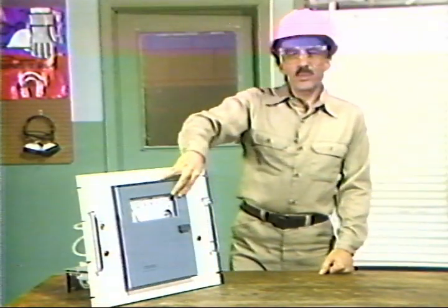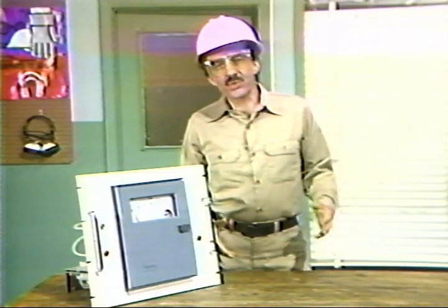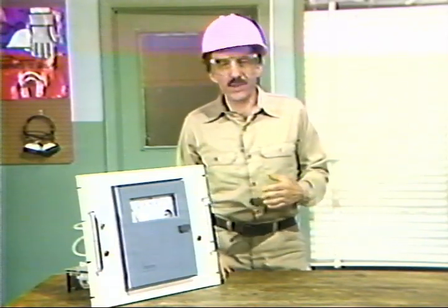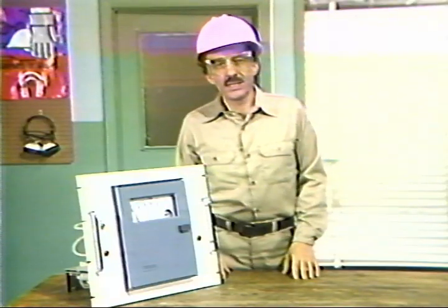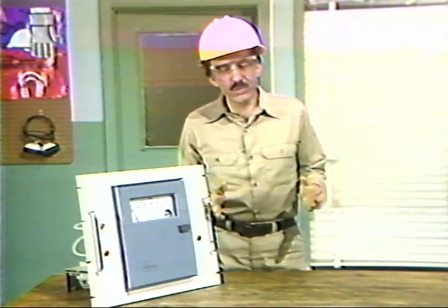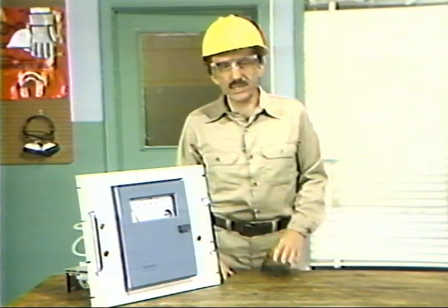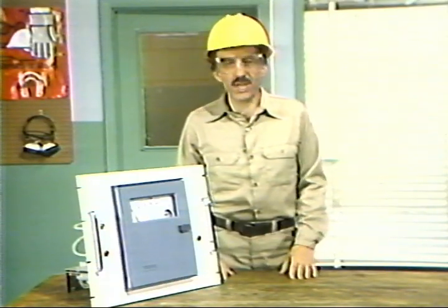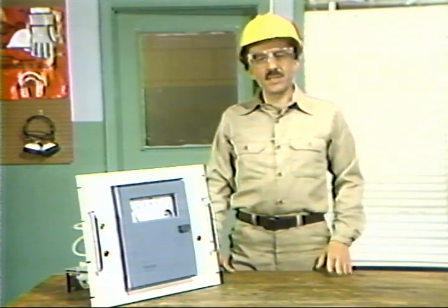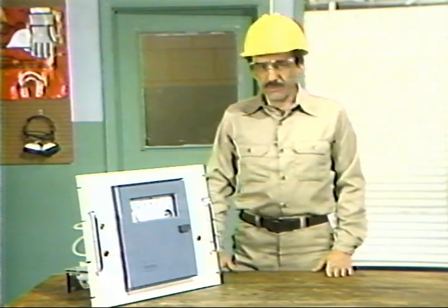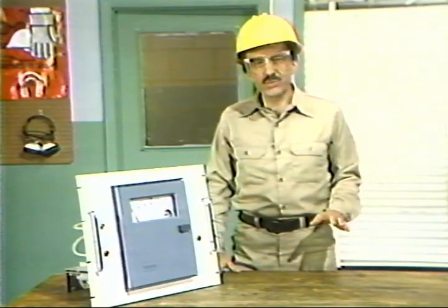In this segment, we've looked at an example of a rate controller. In general, rate controllers project how much a process variable will deviate from set point in a given period of time. Then the controller produces a corrective boost in its output. This feature enables a rate controller to quickly stop a process variable from changing. Now's the time to read the material in your text dealing with rate controllers. When we return, we'll look at a controller that provides all three control modes we've studied so far.